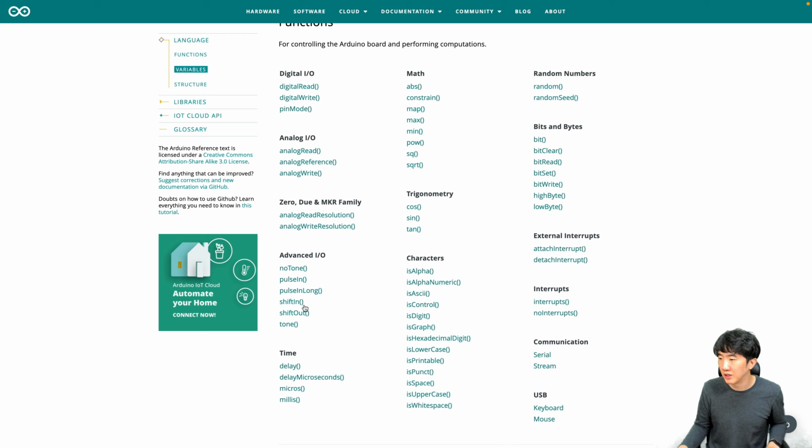These commands are the shift in and shift out functions. You can use something like this, but generally, Arduino provides libraries related to SPI or the wire library for I2C, so you can use those. Alternatively, if you want to control things more at the hardware level, you can use this method.